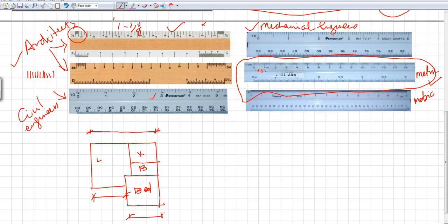Okay, so if I measure on my drawing just 1/8 of an inch, then I already know that in real life, when I do the construction, that is going to correspond to how much? To 1 foot. Okay, now let's check out how big this distance is.